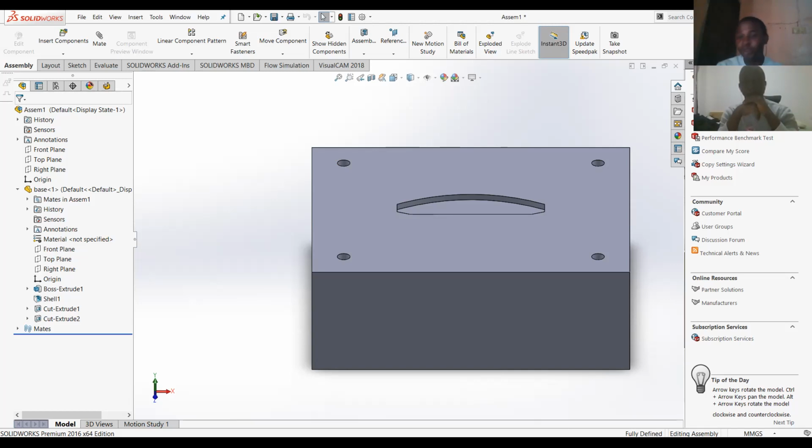That kind of thing in Solidworks is what we call external referencing, when a part changes as a result of another part changing. If you make a new part and base it upon this diameter, and this diameter changes later in the future, the part will definitely take the order and change with it. That one is called a top-down assembly system. What we are starting with is the bottom-up assembly system.